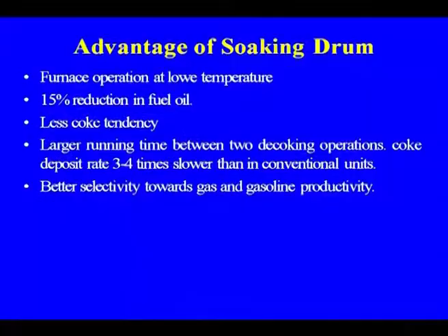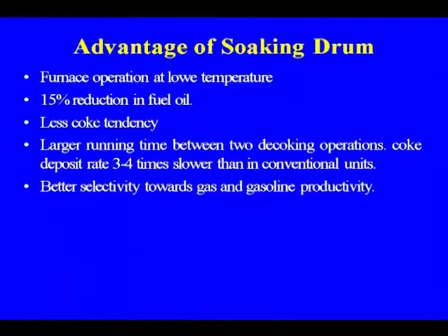Advantage of having the soaking drum in the Visbreaker: the furnace operates at a lower temperature, 50% reduction in the fuel oil, less coke tendency, which I told you because we are giving more reaction time at a lower temperature in the soaker drum, larger running time between two decoking operations, coke deposit rate 3 to 4 times slower than in conventional units, better selectivity towards gas and gasoline productivity.